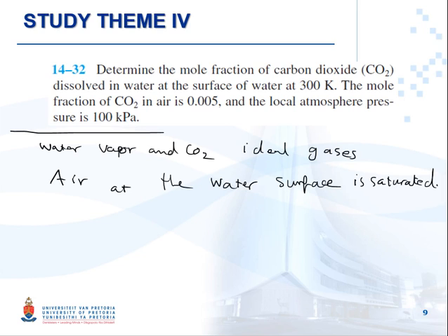So the P sat of water at 300 Kelvin, if we go to the table, we can find that answer to be 3.6 kilopascal.